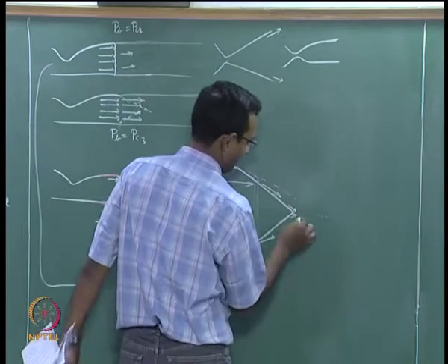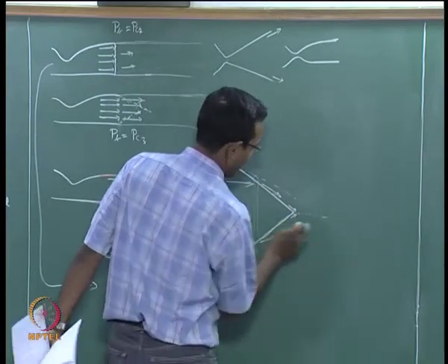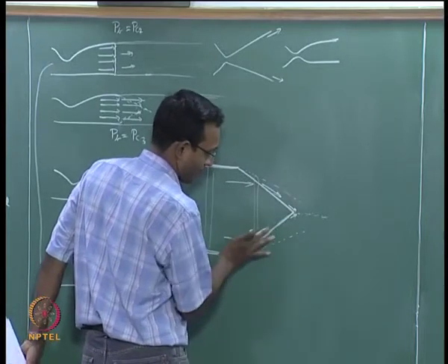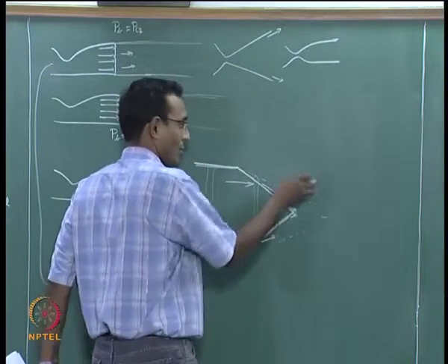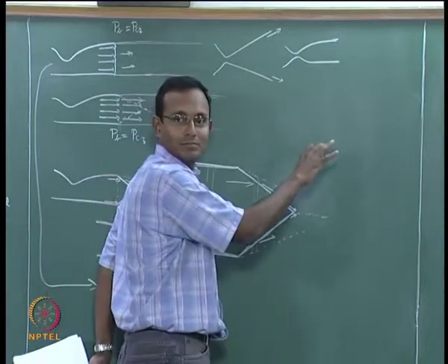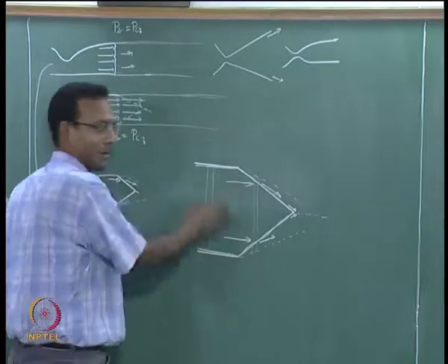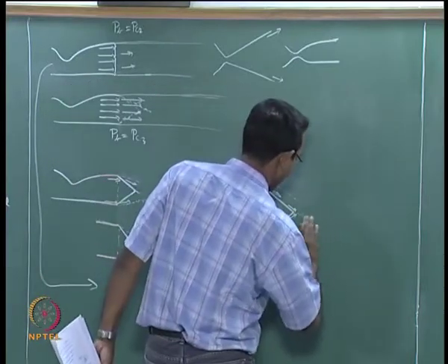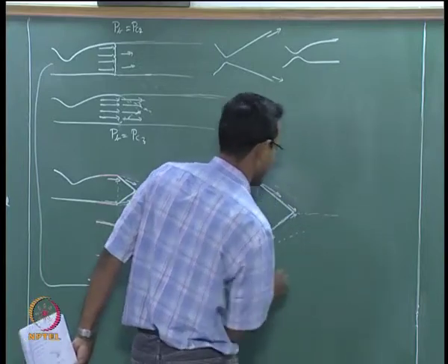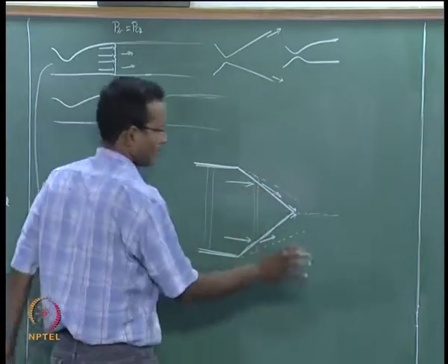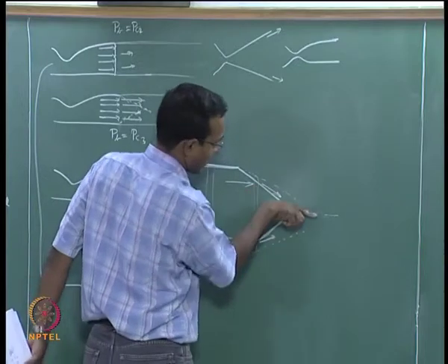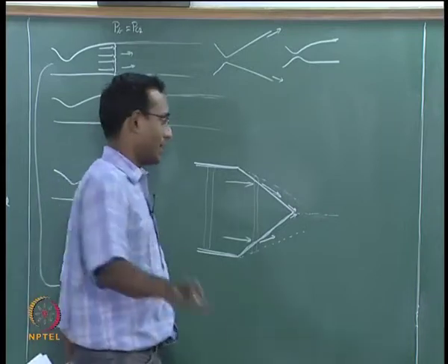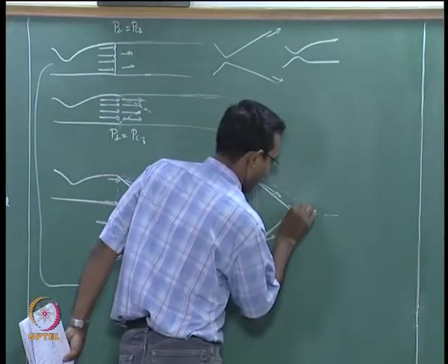drawing some line. I would say that below the line, all the fluid from below will go this side, and above will be all the fluid from above. Typically if it is a symmetric problem, that will be the line of symmetry anyway. Since fluid mechanics has a lot of lines of symmetry, we will just keep the line of symmetry as a horizontal axis for us. So the fluid that is coming at this angle has to now turn back to become parallel to this axis. To do that, there will be another oblique shock.